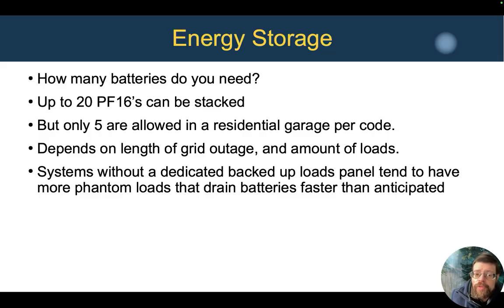But only 5 PowerFlow 16s, 80 kilowatt hours total, are allowed in a residential garage per code. So once you get higher than that, you're looking at separate power buildings to have your batteries and inverters in, rather than having them just in the garage.